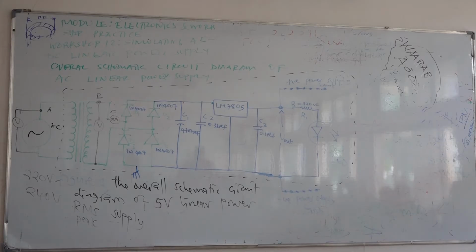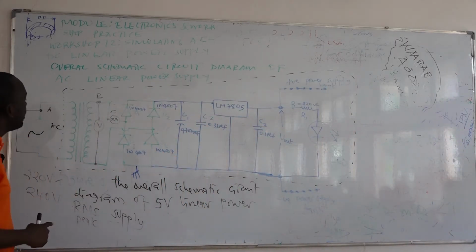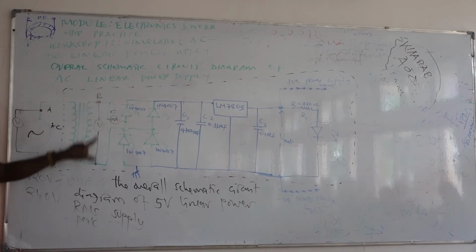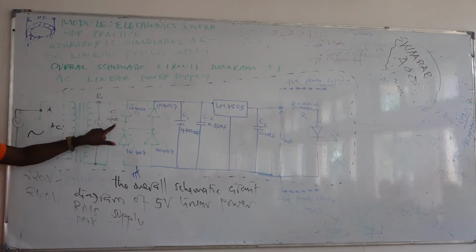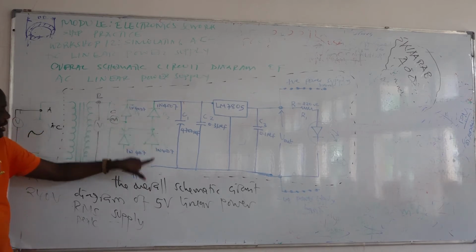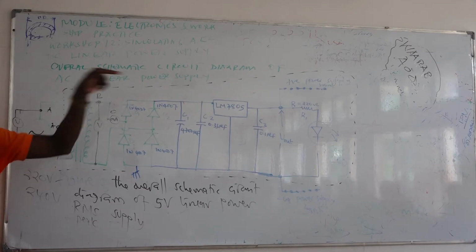Are we together? If you refer to what I taught you in theory, in workshop 3 and especially workshop 4, after measuring the output voltage and output current of the step-down transformer, when we want to measure the output of the rectifier, we have to change this root mean square voltage into the maximum voltage.